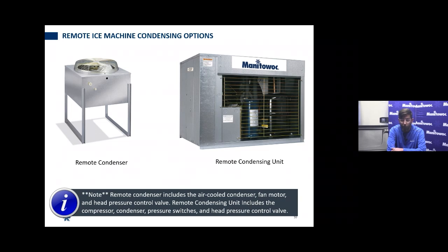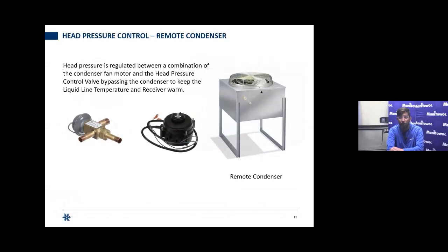On the right-hand unit, we have a fan cycle switch because we're trying to get that discharge heat from the outside unit downstairs, utilizing both a headmaster and shutting off the fan. We don't want to reject heat in harvest. We want to get the heat downstairs, and we're utilizing the headmaster for that. The left-hand unit, we're utilizing the headmaster to keep liquid line temperature and head pressure right, and we'll get into that here on the next slides.